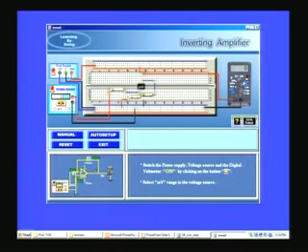I switch on the power supply, all the 3 power supply. So now I can give the input voltages. The input voltage I have choice, I can give in millivolts or in volts. Let me give it in millivolts. So I increase it, 10 millivolt is the input multiplied by 1 plus R2 by R1, 100k by 10k, which is again 10. So 1 plus 10 is 11, 11 times 10 millivolt is about 111 millivolts, 110 millivolts, that is 0.1 volts, that is what you see here. So I can apply 20 millivolt, then the reading becomes minus 0.2 volts or 200 millivolts.